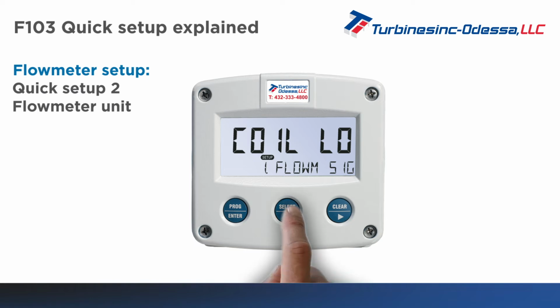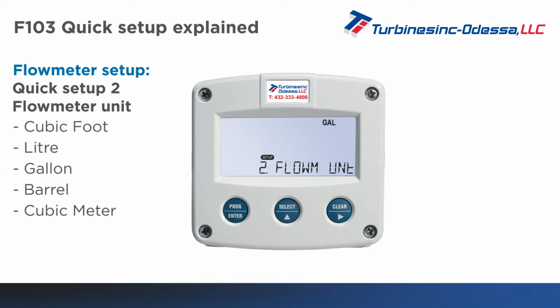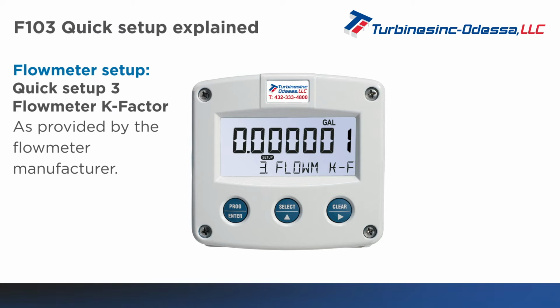Quick Setup 2. Here you can set the calibrated measuring unit for the flowmeter, cubic foot, liter, gallon, barrel, or cubic meter. Quick Setup 3. Here you can enter the K-factor for your flowmeter as provided by the flowmeter manufacturer.